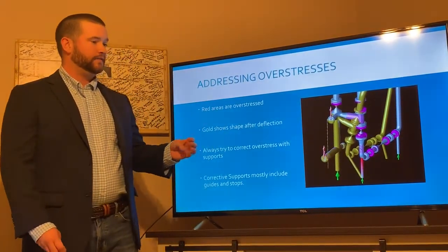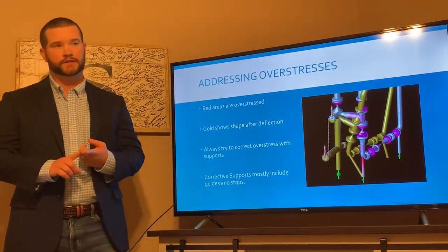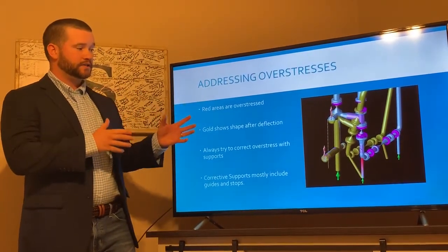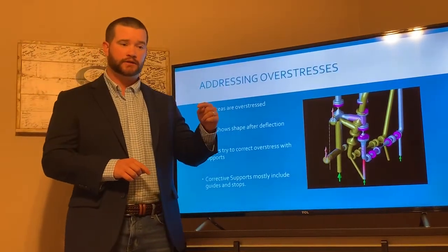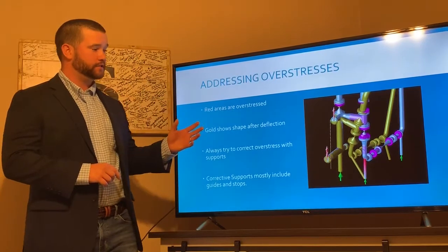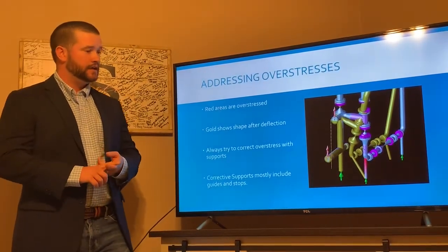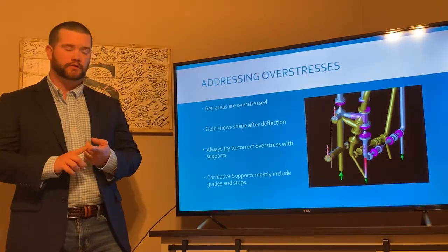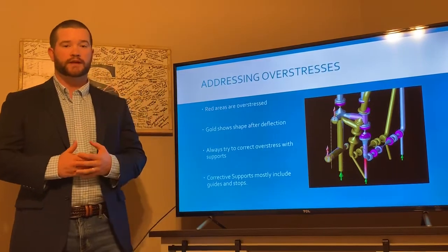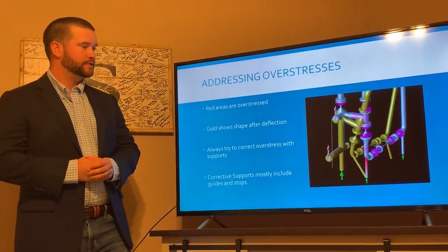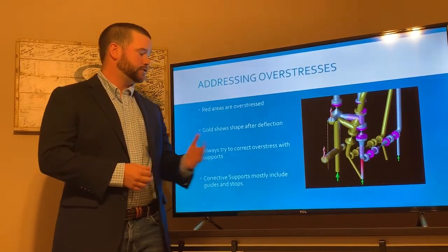The key to finding a solution for these stress systems is, how do I change the system as little as possible? If I can add one support in a location, that's a small change. And if that fixes the problem, then that's what I'm going to go with. I'm going to start off with small changes, maybe add a support or restraint. And if that doesn't work, then you're going to have to get into your more complicated redesigns of your piping systems, and you're going to have to reroute your pipe a different way that mitigates those stress issues.